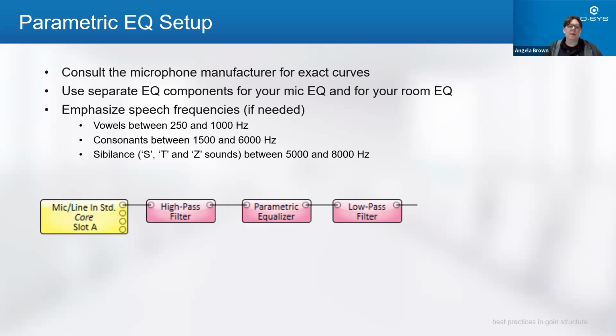One other thing, remember that as you remove or add frequencies, your gain is going to be affected. So if you cut, let's just say at 1K, minus 30 dB, yes, you're only taking minus 30 dB at 1K, but you are taking out signal. So as you go through these, you need to pay attention to making sure your signal stays where it needs to stay to process it.